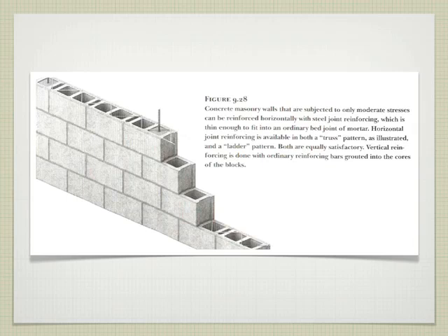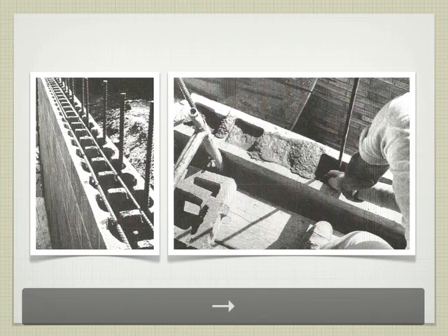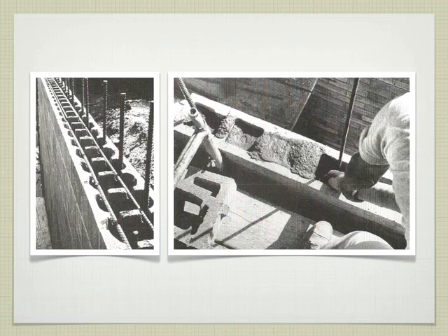The advantage there, though, is we don't have to build formwork because the formwork already exists. So it's a good economical way, which is part of why we see a lot of freeways that have this kind of work. It takes less. So here we've got our concrete blocks. Notice that we've got a channel for rebar running through this. Likewise, this particular block is a good example of that. We have a hole here that allows us to run reinforcing through it. So if I flip this over and run it that way, I could put reinforcing in here, which would help tie the wall together.